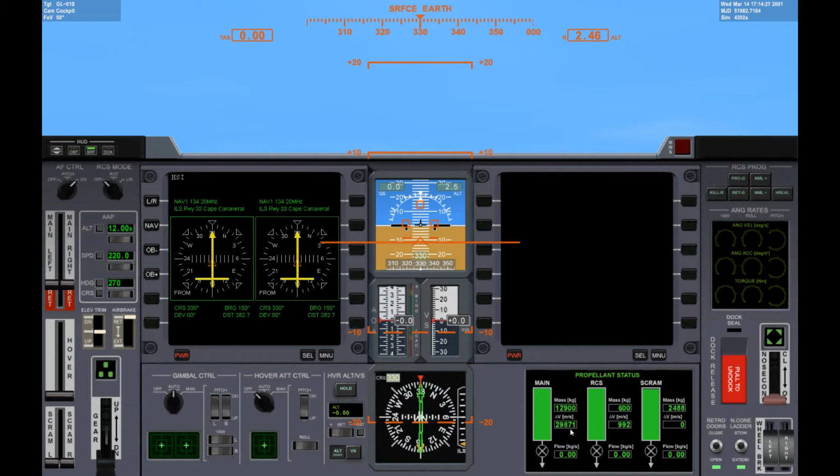To land on the moon, you need the 9,600 plus you need about 3, so that puts you up to about 12,600. Then you have to get into orbit around the moon, which puts you at about 13,600, and then you have to land, which puts you about 14,600. So you need about 15 kilometers per second, 15,000 meters per second.